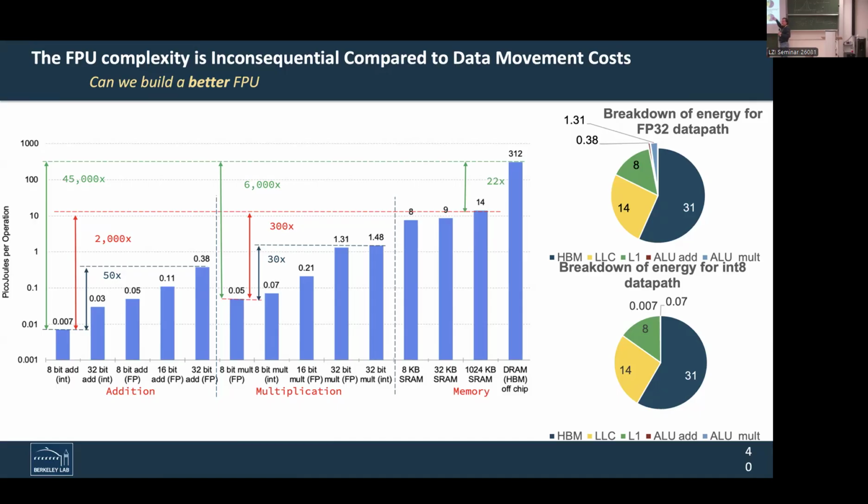Then the other part of it, going back to Jim's point, is how many times you use the data, because if you want to get peak performance out of your GPU or whatever processor you're using, you need an arithmetic intensity around 700. So take your ALU number, multiply by 700. I have a spreadsheet model. We're going to go back in, fix this, and then experiment with different reuse numbers and see how this plays out. I don't know if I can achieve 700 average reuse. I haven't seen that in many.